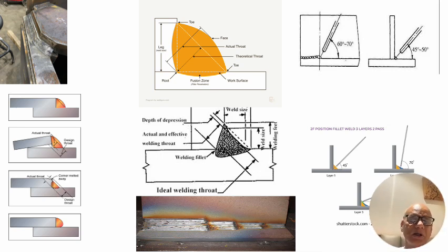And that's because, once again like in the butt joint, here we have the least weld, and here we have the very large width of weld which is going to shrink. So the shrinkage here is less, shrinkage here is more, and the natural tendency for the vertical member is to bend down towards the horizontal member because of this larger width of weld which is going to shrink.